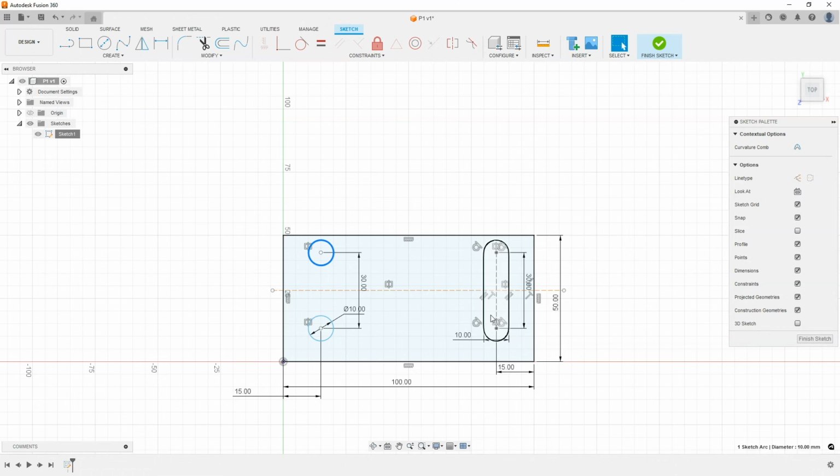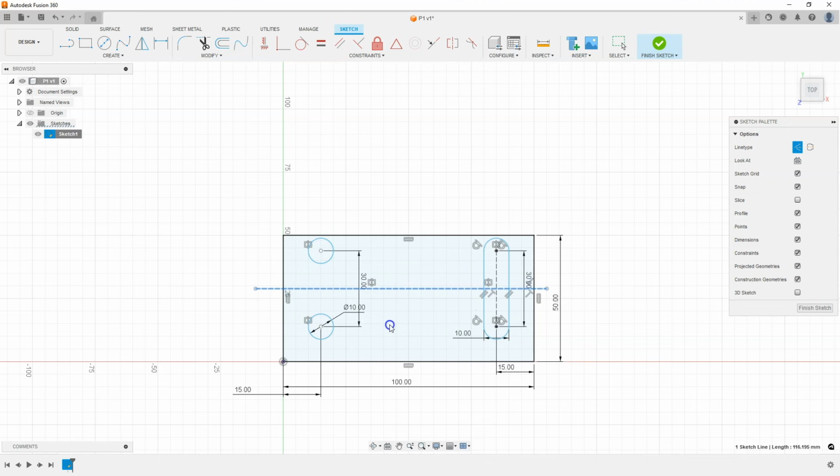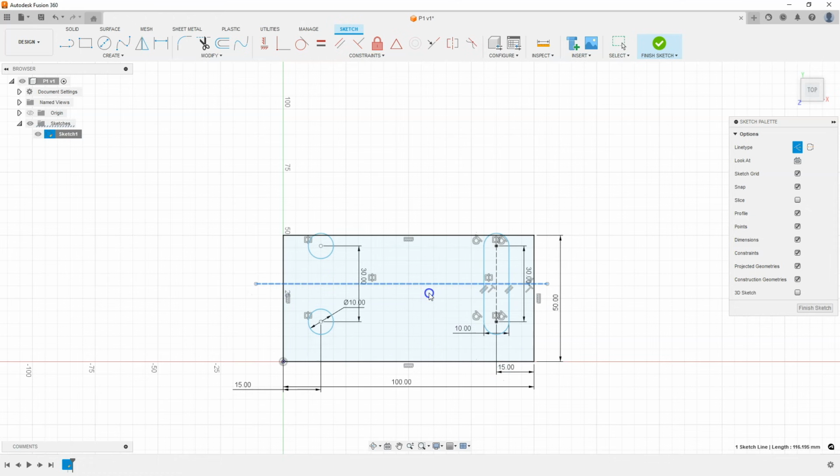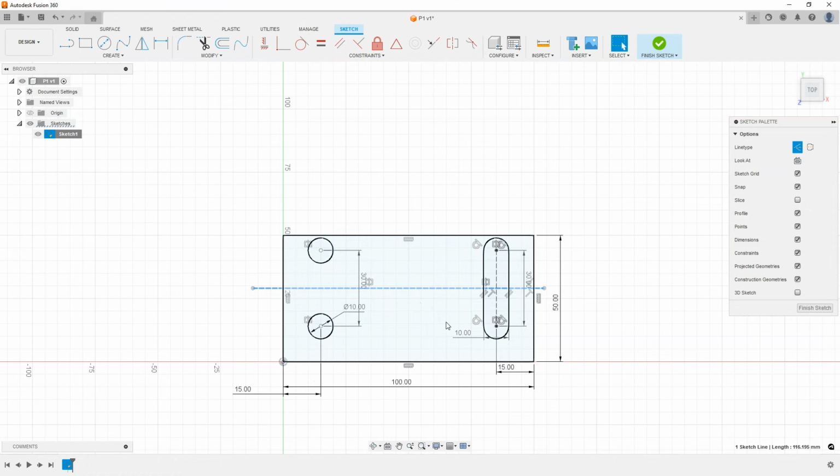And in this case, the construction line that was supposed to pass through the center of the rectangle is not associated with the rectangle. The rest of the geometries are constrained to this line, and the distances of the geometry from the edge of the rectangle are added, but this line has no specific position in the y-axis. So all geometries except the rectangle can be moved along the y-axis. Let's add a symmetry constraint here so that the construction line lies in the center of the rectangle.